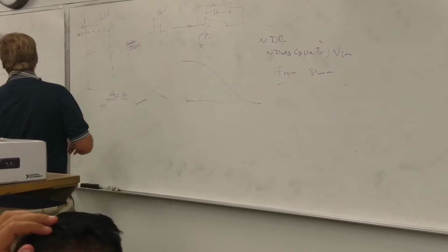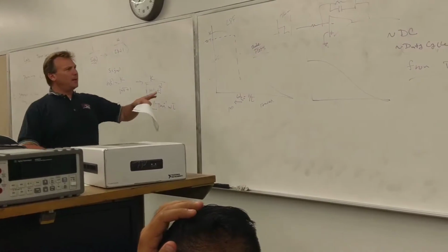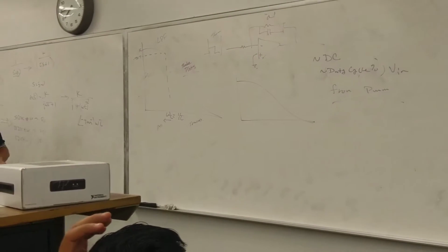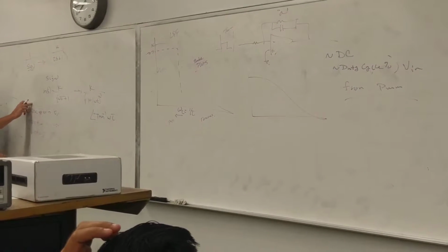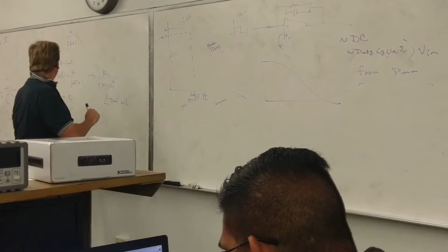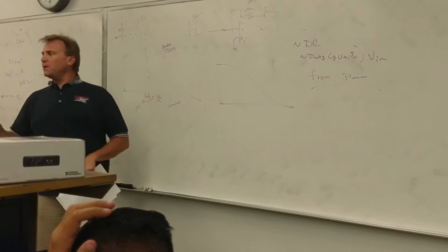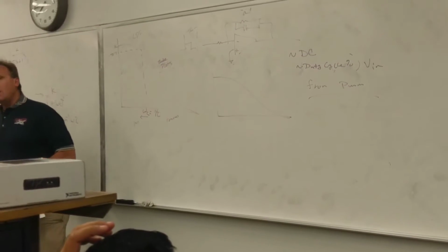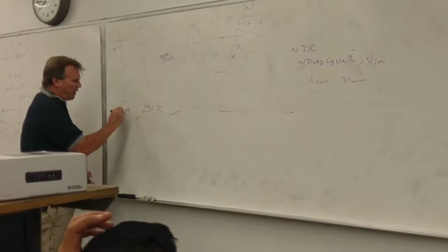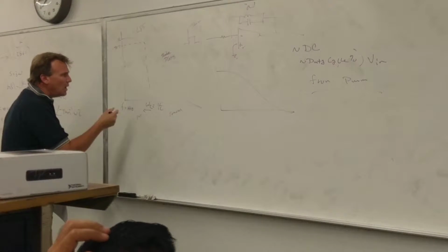So for the lab, you're going to generate this PWM, and you're going to apply that PWM to this signal. And what I want you to do is to sweep the frequency of your signal. No, I take that back. Part 1 is build a PWM. Part 2 is to build the circuit using the function generator and the oscilloscope. What you're going to do is start with a frequency of, say, 1 hertz, or maybe 10 hertz. What voltage do you get? So here's what we're going to do.